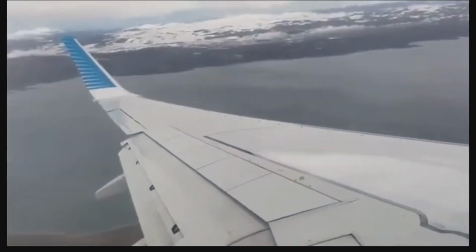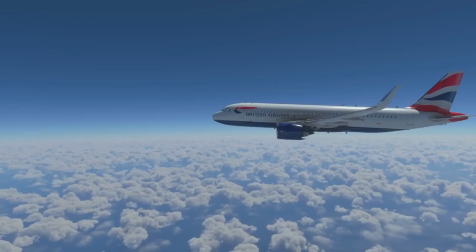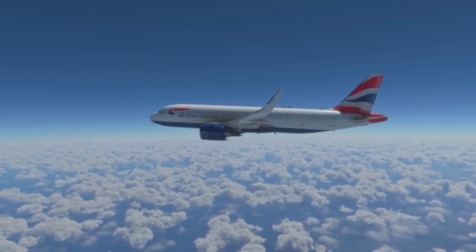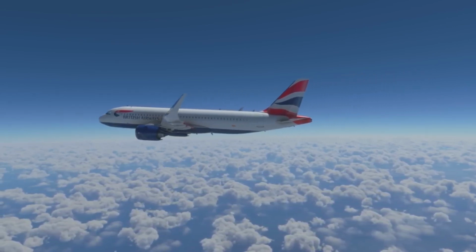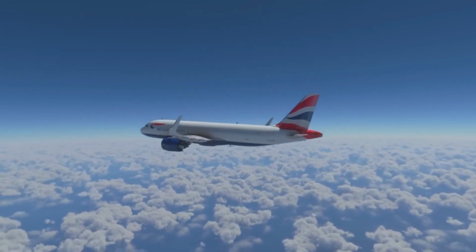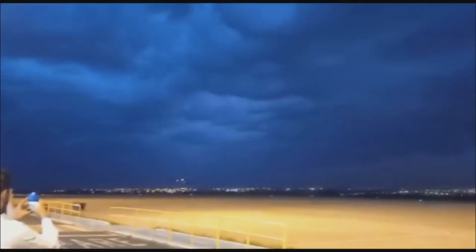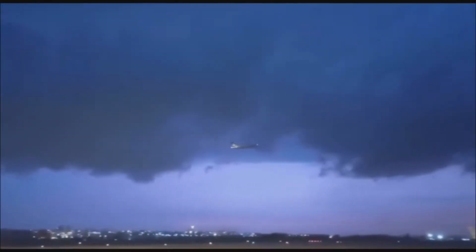When landing from power approaches in turbulence, the touchdown is made with the airplane in approximately level flight attitude. The pitch attitude at touchdown would be only enough to prevent the nose wheel from contacting the surface before the main wheels have touched the surface. After touchdown, the pilot should avoid the tendency to apply forward pressure on the yoke, as this may result in wheelbarrowing and possible loss of control. The pilot should allow the airplane to decelerate normally, assisted by careful use of wheel brakes, and avoid heavy braking until the wings are devoid of lift and the airplane's full weight is resting on the landing gear.